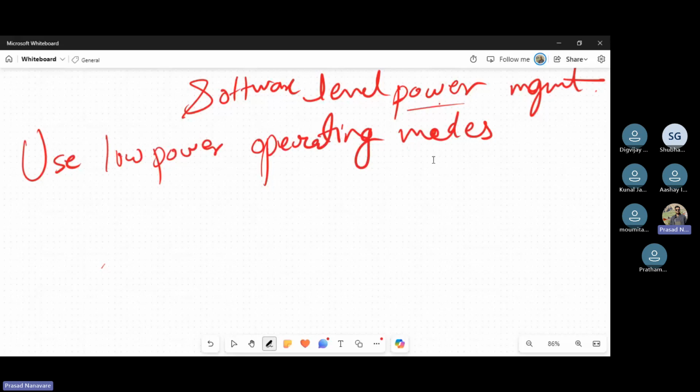Like I explained in the last slide, like idle, sleep, deep sleep mode वगैरह, ठीक है. तो ये सब मोड जो होते हैं स्लीप मोड में, like many embedded systems support sleep modes when the processor stops most internal operation, except the essential tasks. So that is sleep mode. Then idle mode is basically the processor ka core idle. Okay, but the peripherals are still active.